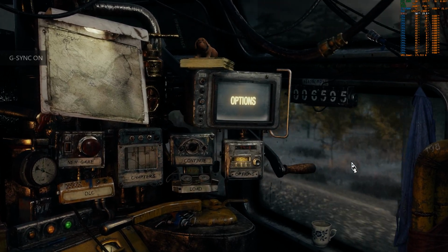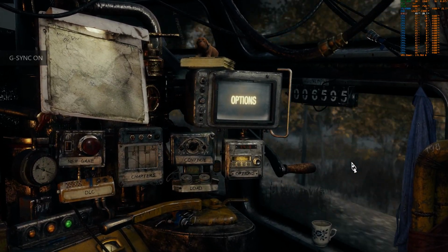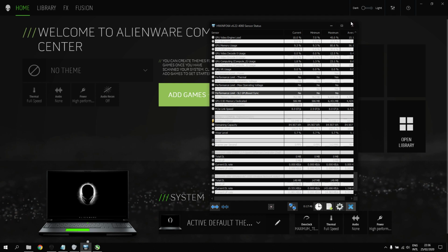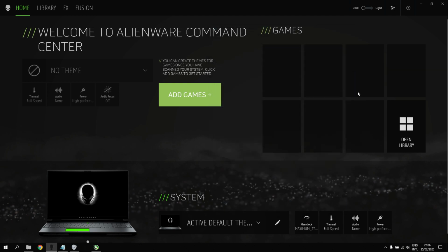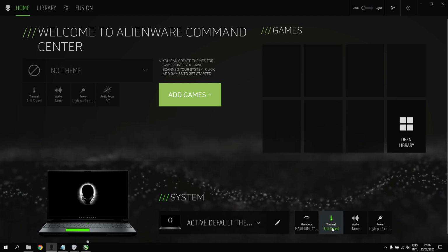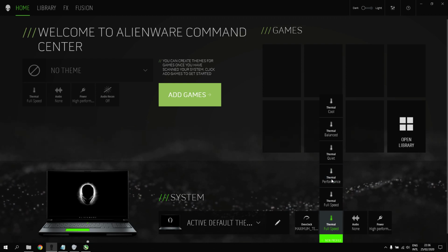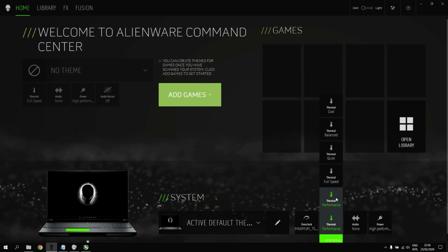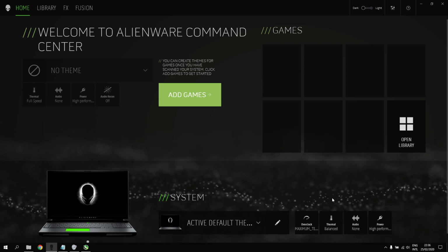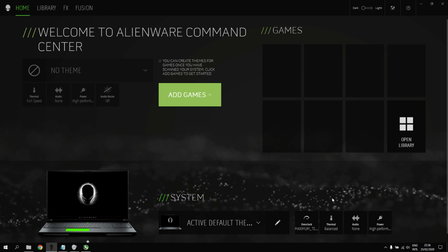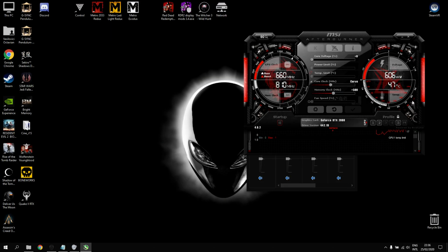So I really hope you enjoyed this video, guys, and it showed you and you understand how you can overclock and undervolt your GPU, how you can bypass the BIOS thermal lock or hard thermal throttle. I was still on performance. Was I? Interesting. I think I was on full. Anyway, how you can bypass the thermal limit on the GPU side using HWiNFO, and how you can create your custom profiles, like I showed.